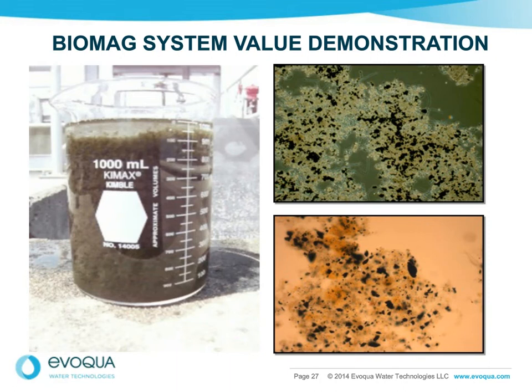So if it's 3,000 milligrams per liter of mixed liquor, we'll maintain 3,000 milligrams per liter of magnetite in the process, so a total TSS of 6,000. Now, because the magnetite gets embedded into the biofloc itself, it flows very similar to 3,000 or 6,000 milligrams per liter of solids. It just settles a lot faster than it would conventionally. So from a pumpage standpoint or movement around, it's very similar to the mixed liquor concentration because the floc particles are still roughly the same size.